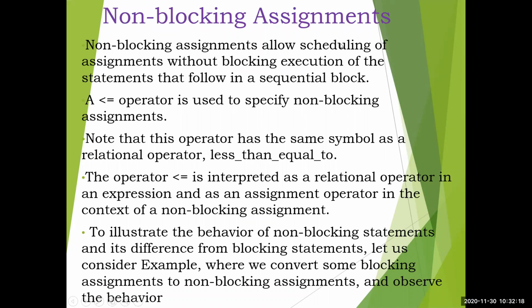Non-blocking assignments allow scheduling of assignments without blocking execution of the statements that follow in a sequential block. So it does not follow the same example. It will not wait for count equal to count plus 1 to wait for the previous block. They will be executing in parallel and they will end at different times. So that is non-blocking.